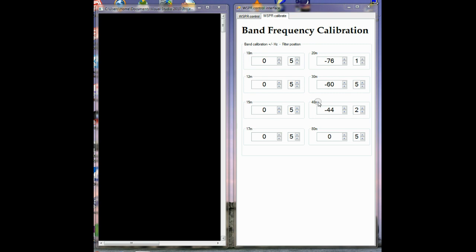It adds an offset to how it's programmed. Now these modules will drift with time, based on temperature, aging effects, various other parameters. So you could potentially expect a drift of 1 or 2, maybe quite a lot of ppm per annum, depends on the conditions. So these offsets will need readdressing at some point, if you're that bothered. So that's frequency calibration. And now the second parameter is the filter position. That's not strictly to do with calibration, but it just seemed a convenient place to put it.